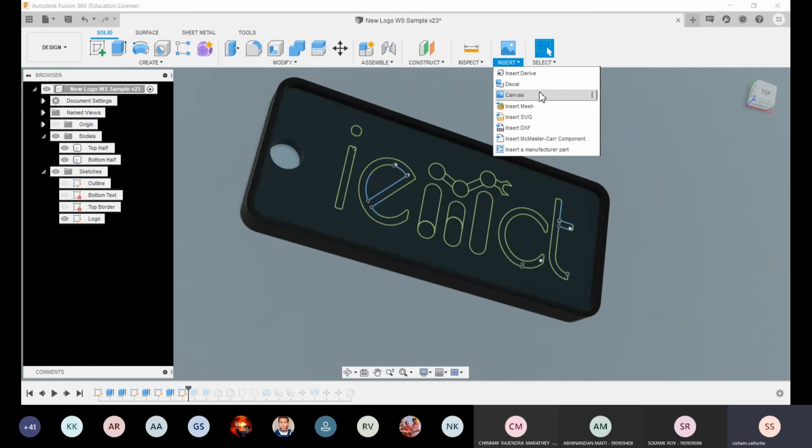So in one example, which is shown here in the tooltip, if you want to make a car, you can just make a sketch or any file in an image format, which could be a JPG or PNG file with your photo that you want. And then you can scale it to the size that you want in Fusion and then use that as a template to create all the points and then maybe create surfaces and bodies to actually bring that design out in 3D.